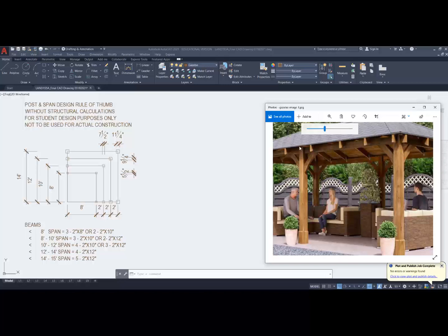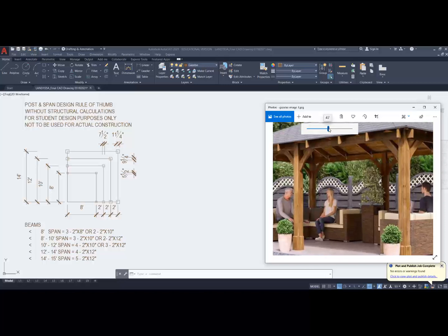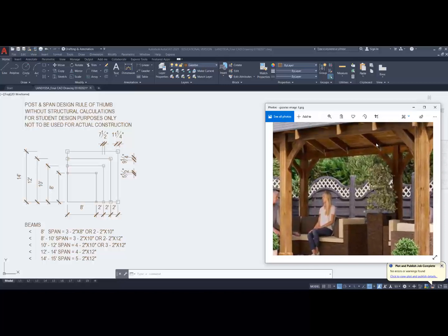And the joists are actually sitting, they're notched out and sitting on the beam. Now, typically we cover this. We use a fascia board, but it may be a nice look to have this exposed. These are actual structural braces which reduce the spans, and we'll talk about that next semester. But you can see how the joist sits right on top of the beam.